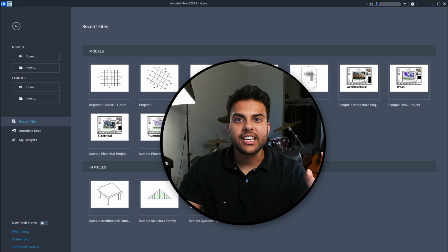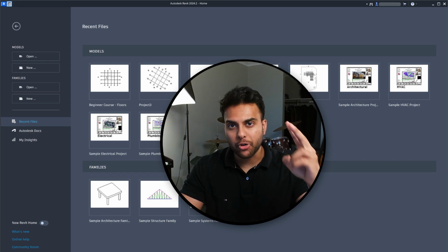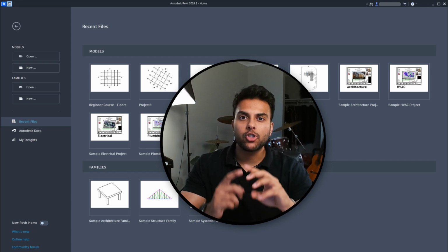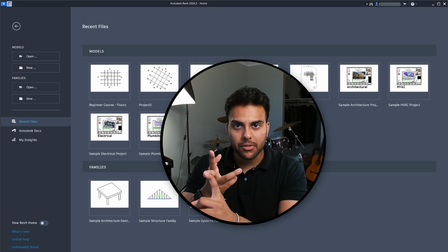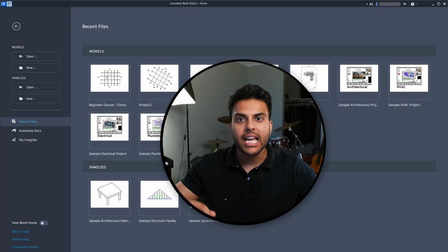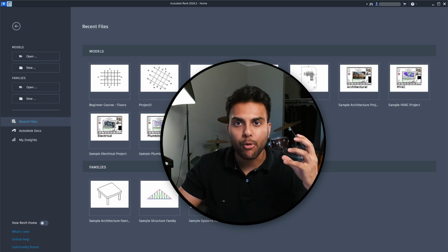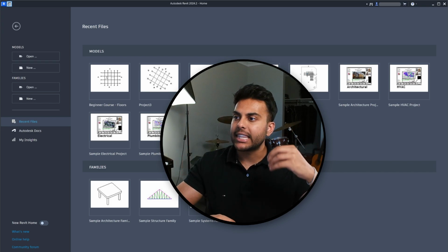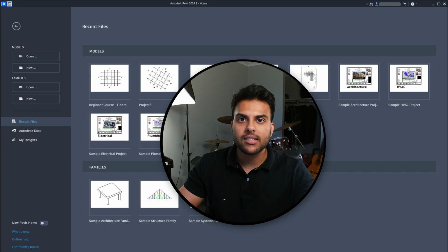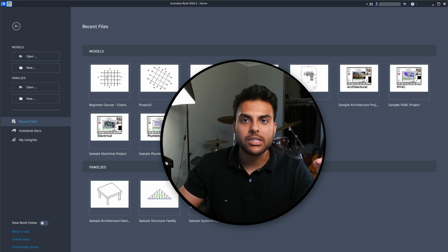In this video, we're going to set up a brand new Revit project for architects. We're going to set up levels, grids, and elevations, and then we're going to talk about project base points and survey data, right? We're going to bring our survey data from site into our project, set up our true north and our project north so that we're able to start modeling properly, so that everyone can link our project into their templates as engineers or any other subcontractors, and they're going to be able to have a really good and seamless integration with their Revit models as well.